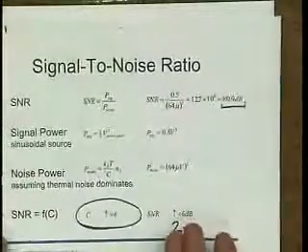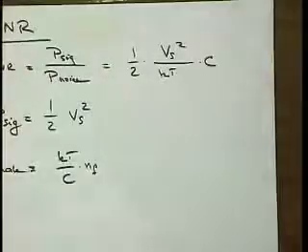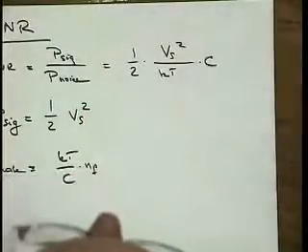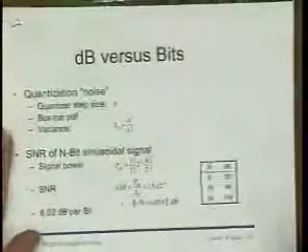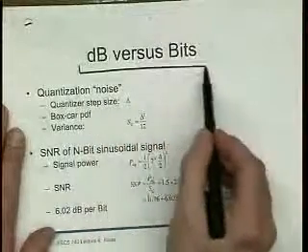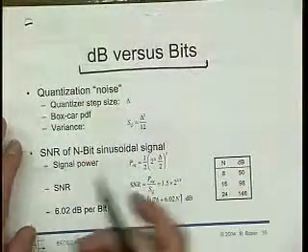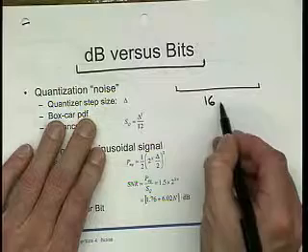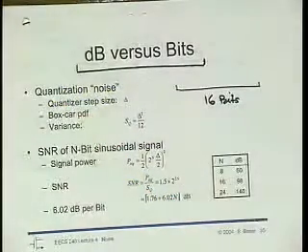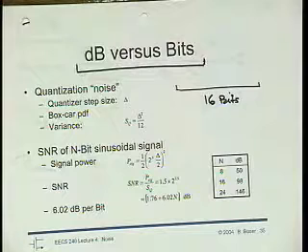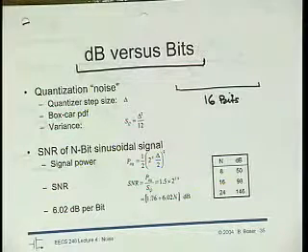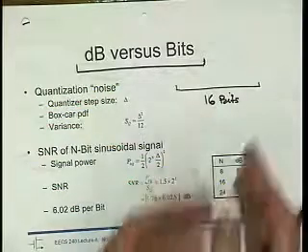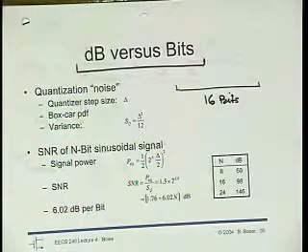Now let's put some meaning into this dB stuff. The best metric is to relate dBs to bits. I think we briefly mentioned that before. If in a computer we represent a number with a finite number of bits, let's say 16 bits, then we cannot represent the exact value, perhaps, that we want to store, but we instead make a quantization error. Right? We have to quantize, round to the nearest integer that can be represented with just 16 bits.